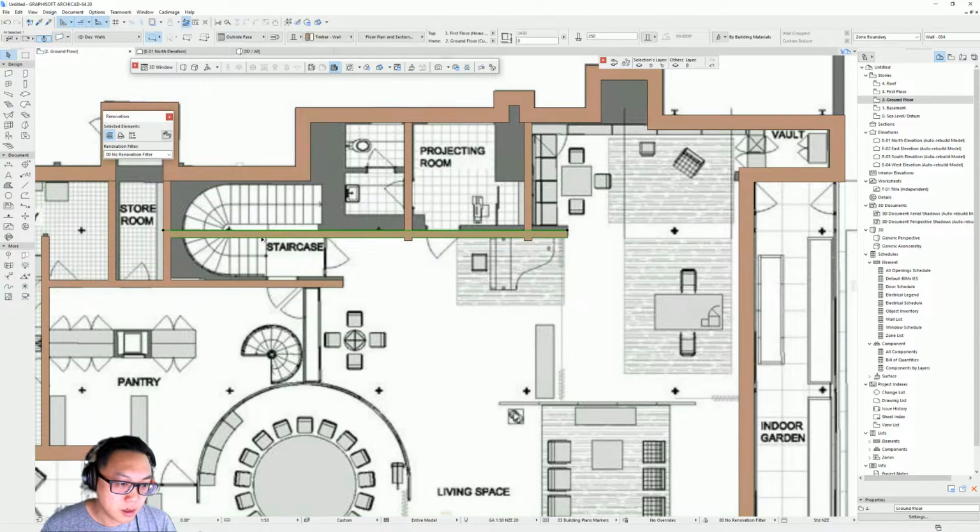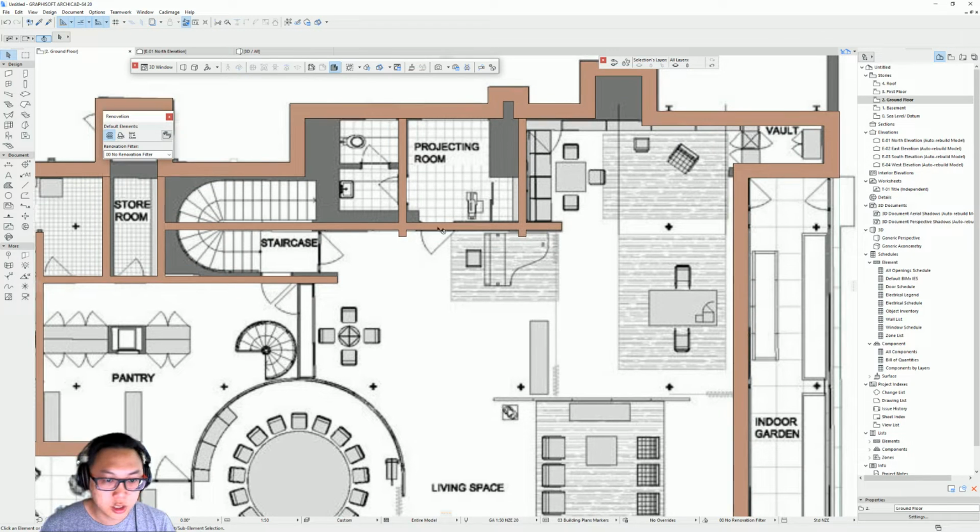And you can change the line, so now it's set on the outside, but I can just center it so it moves. It's nice in the right position, and I just have to cut those walls. So I'm just gonna press Ctrl, scissors, and click.